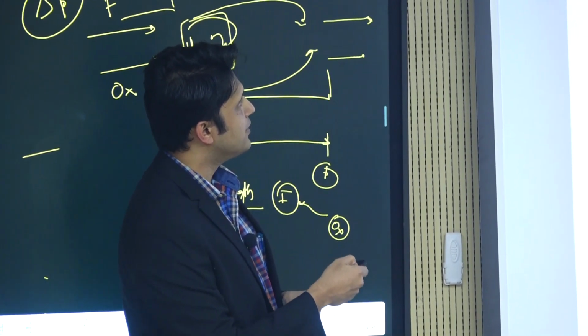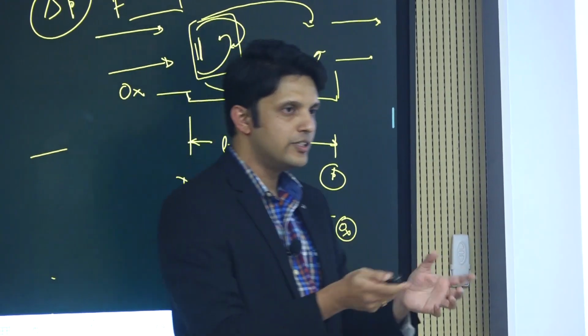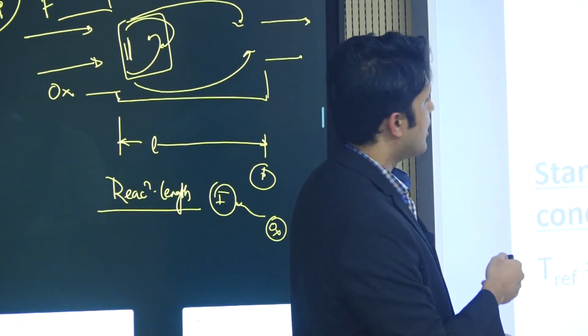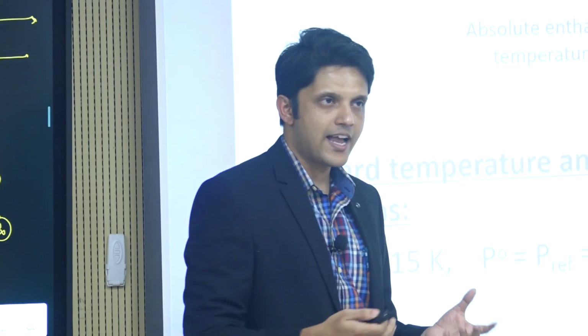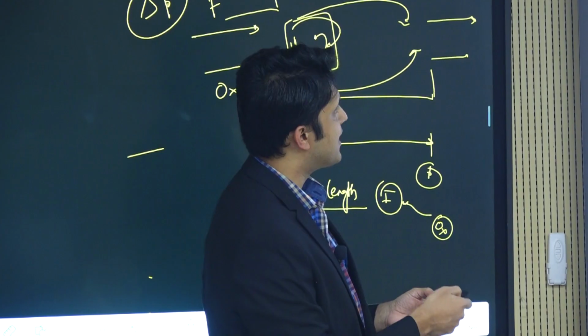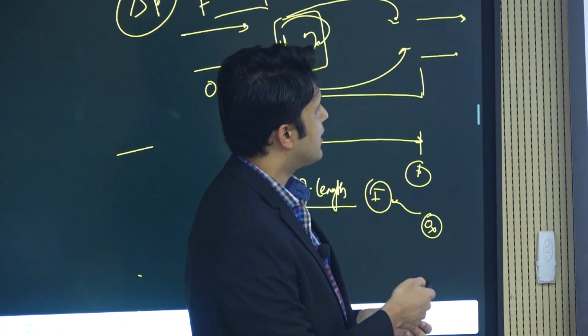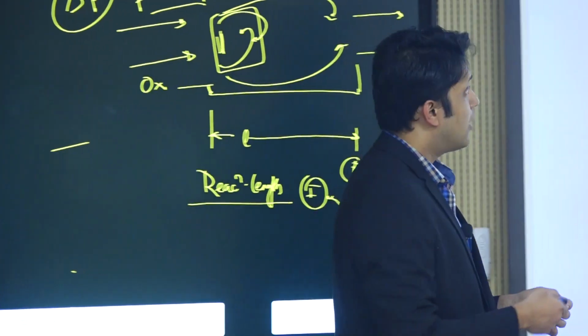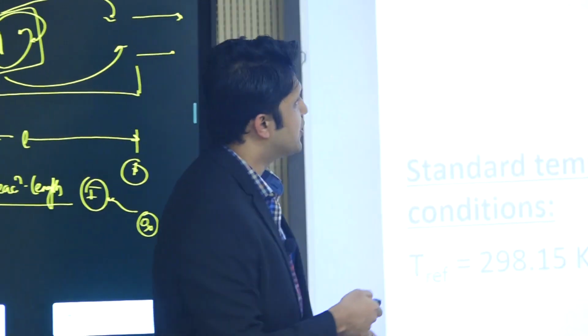Now once you form that species and give that volume in your environment, you call it the enthalpy of formation. And if you are preheating, let's say your gas is at a higher temperature, then you also have additional enthalpy that is added, that is called your sensible enthalpy. That is the amount of energy that you need to raise the species to the desired temperature. Alright.